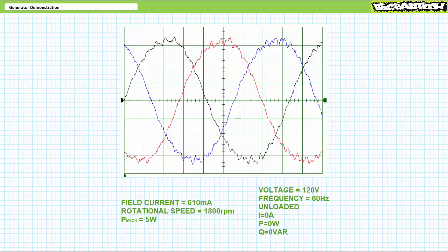A quick solution to this problem was to increase field current. This being said, there are practical limits of compensation. We demonstrated too high of an inductive demand might result in the generator not being able to meet the desired specification despite pegging field current to the max.